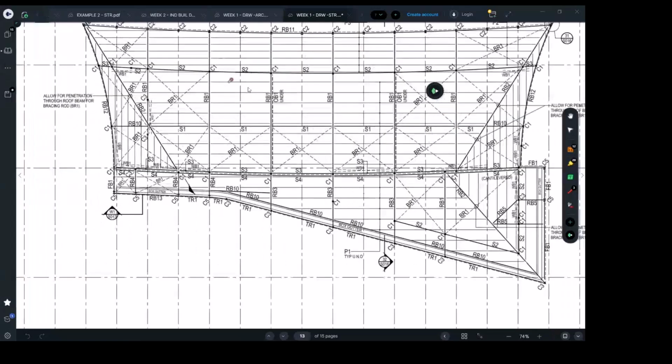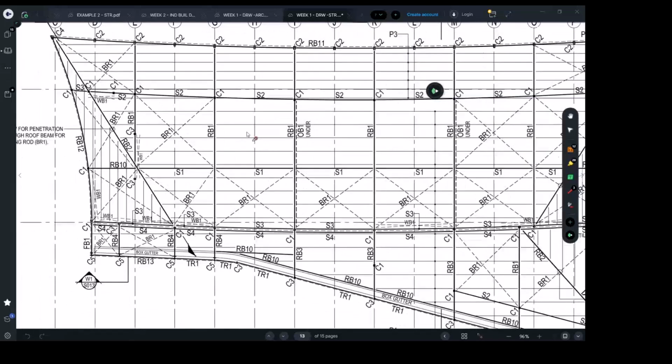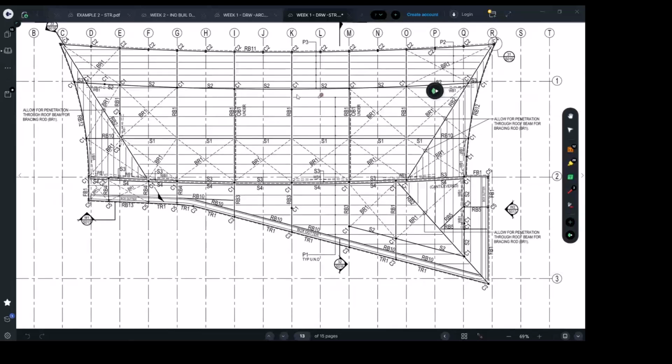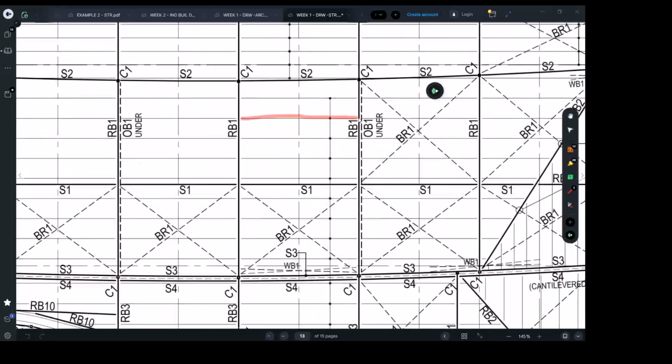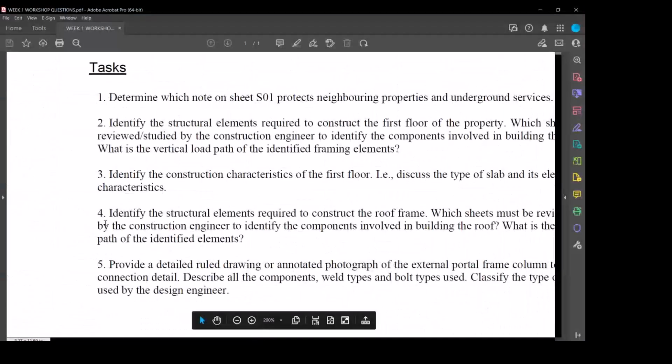The elements are the purlins, the roof beams, the columns, and the roof bracing, which I will talk to you a lot about this week and next week. Roof bracing will stabilize the roof for us and take the load to the wall bracing, lateral loads, right? And the load path, as I said, the sheets put weight on the purlins, which put weight on the roof beams, which put weight on the columns, and that's it for the roof, because the first floor slab will take care of the rest.